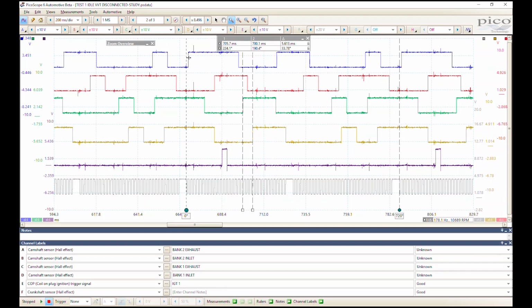Alright, so that's the technique. The first rising edge after our measurement point here, using IGT to denote which of the missing tooth or missing teeth we're going to measure from. Okay, so this helps us identify the missing tooth as our reference, our clock signal if you like, our point of initial measurement, and then the first rising edge of each camshaft. Well, that's a falling edge after that point. The first rising edge is this one. Same again, there's a falling edge. We'll go for the rising edge. So remember, you've got those values there.